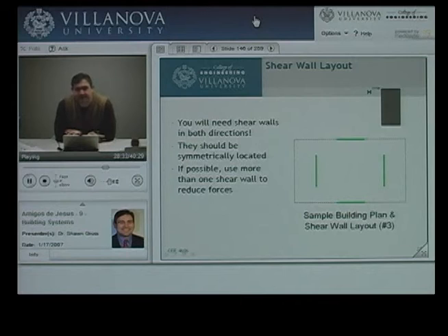Also realize that in just about every project, there's going to be a give and take between the architect and the engineer and or the contractor. So it is not unusual for you to say, hey, I really can't find a good shear wall location here. Can I propose that maybe we work around this by shortening this window or adding in something here? So those kinds of gives and takes are possible. You need to look at it, again, in the context of your particular structure.